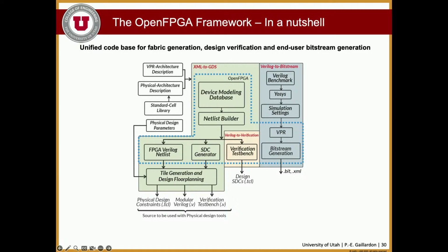If your tool is capable of internally representing the architecture and generating routing resource graphs, then it becomes pretty easy to just dump this data structure, dump the topology of the fabric that you have described, and then go through the physical implementation. Not as simple as that, because you need to think about a bunch of physical design aspects, on how to place and route and physically implement that piece of silicon, but that's the idea.